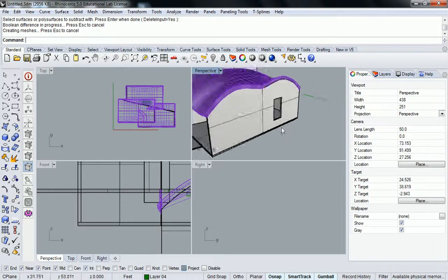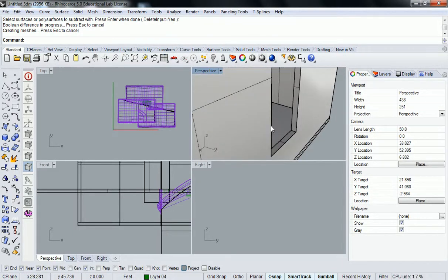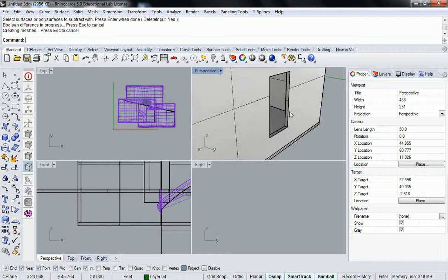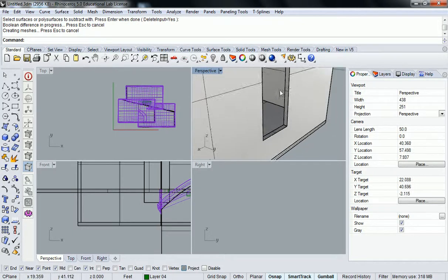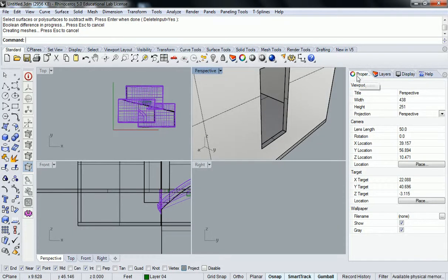However, what we need to do is give it a lot more detail so that when we see it, if we cut a plan, we've already got all the line work that we need right there in AutoCAD. So it's actually going to turn out to be pretty special, I think. The easiest way, I think, to create a simple frame is to give yourself a rail and do a sweep. So it looks a little bit like this.